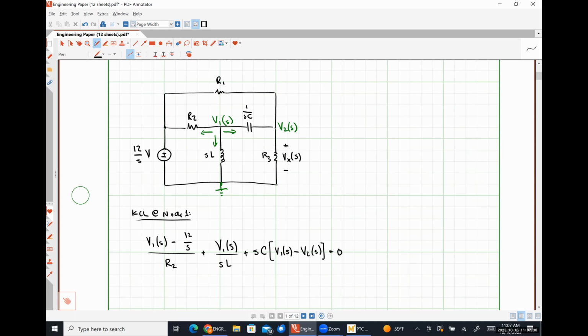So before we move along from this, does anybody not understand this equation? Hopefully fairly straightforward. The only thing that might be a little odd is that when we divide by 1 over SC, that's the same thing as multiplying by S times C. So effectively what we're doing is just multiplying the conductance of that capacitor by the voltage in order to express the current. All right.